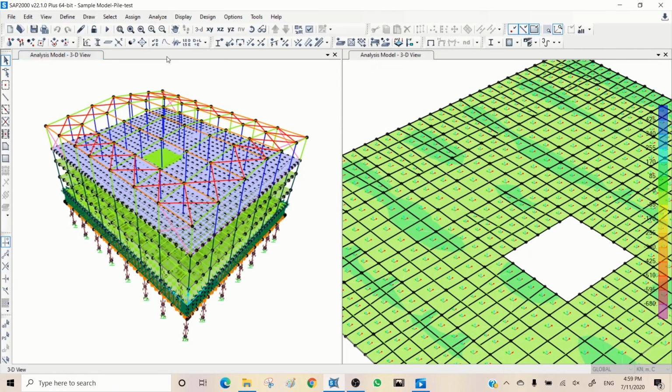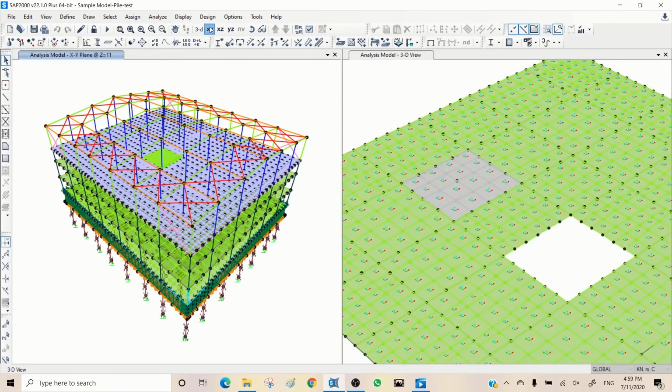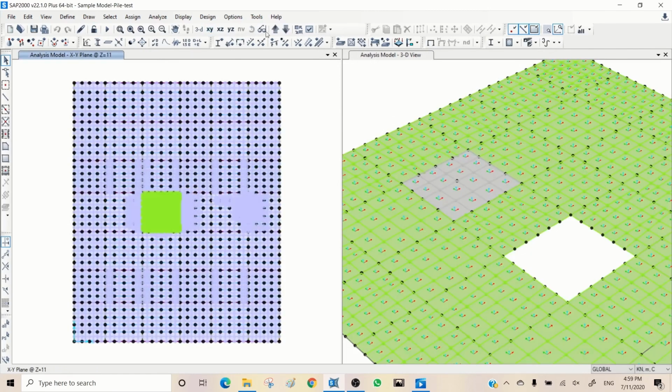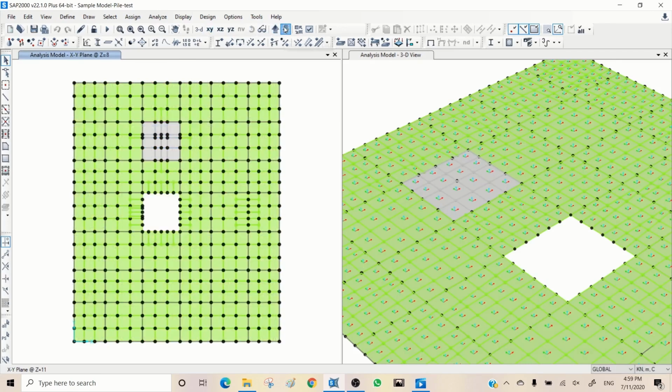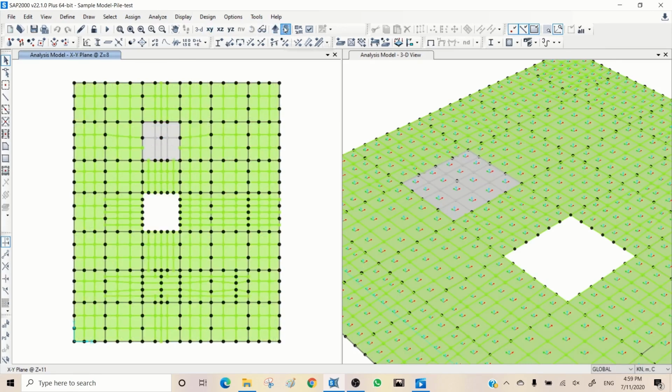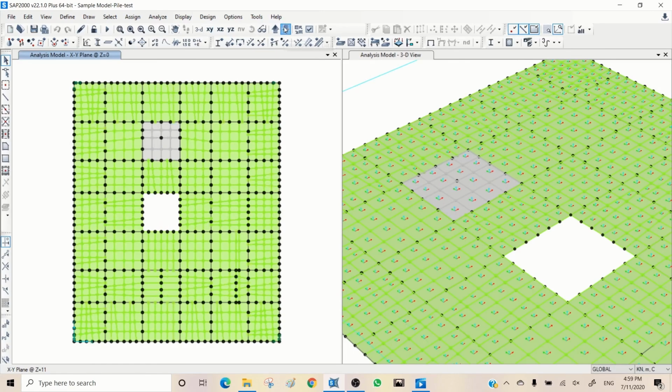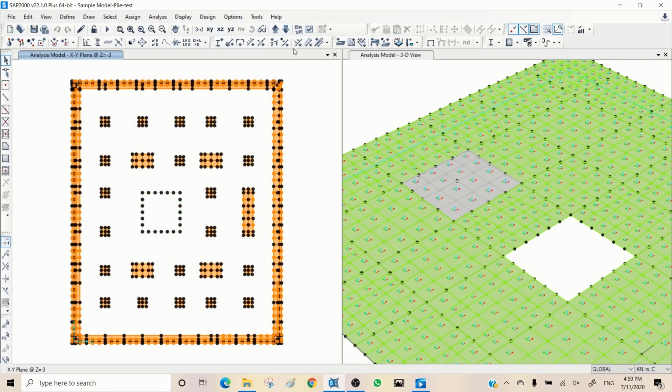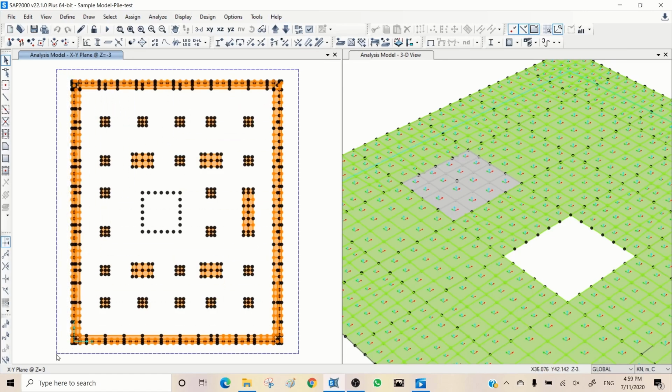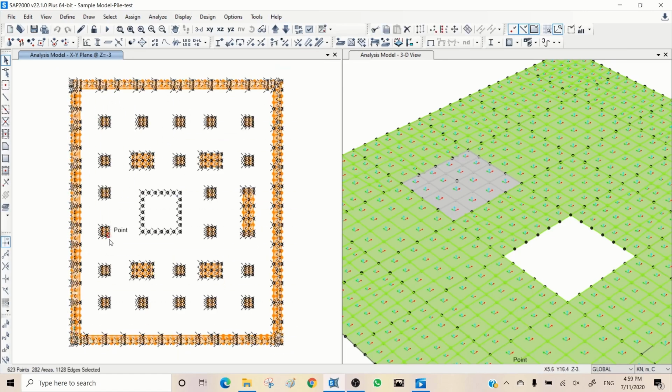Then in the test model, what I will do, I'm coming to the base, which is my foundation. You can choose your base from ground floor because we discussed that, but for modal analysis my recommendation is keep your support to the end. Don't remove your basements. Make it more accurate and reasonable in terms of behavior.